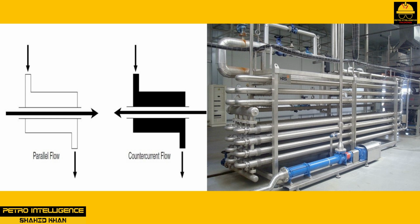The liquid close to the pipe is hot, and the liquid farthest away from the pipe is cooler. Any type of turbulent effect would tend to break up the static film and transfer heat energy by swirling it around the chamber. Parallel flow is not conducive to the creation of turbulent eddies. One of the system limitations of double pipe heat exchangers is the flow rate they can handle. Typically, flow rates are very low in a double pipe heat exchanger, and low flow rates are conducive to laminar flow.